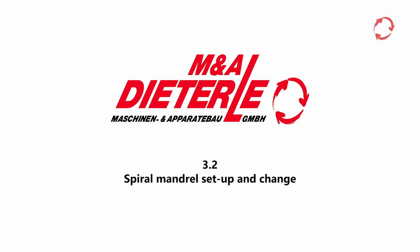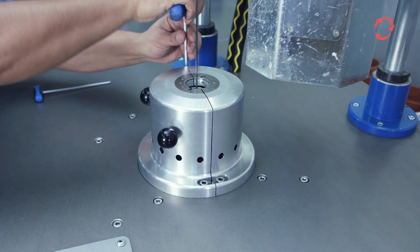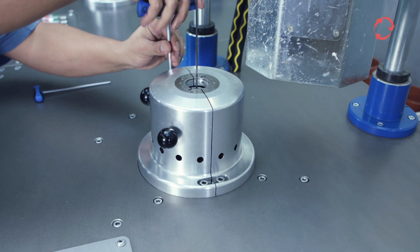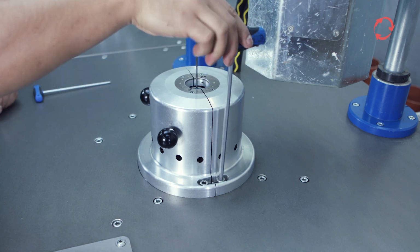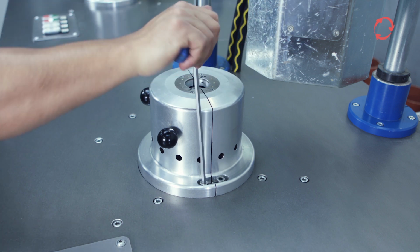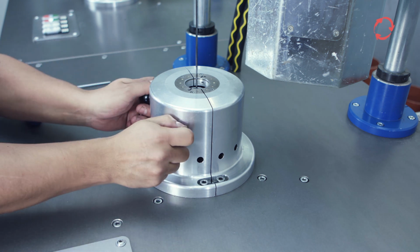This procedure is only necessary for changing the spiral size or monofilament. A long 3mm and 6mm Allen key is required for changing the spiral mandrel. Loosen the screws on the front cover of the winding head with the 6mm Allen key. The housing half can now be removed at the front and set aside.